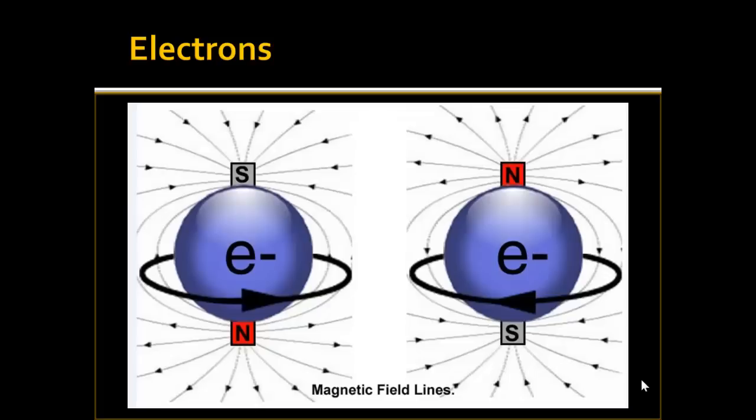They place it inside of a really strong electromagnetic field, created by electricity flowing through a coil, and by a conveyor, it goes into that field, and the magnetic force from the coil with the electricity running through it forces all of these domains, the ferromagnetic material molecules, to line up with all their north poles in one direction, south poles in the opposite. At that point, it is a very powerful magnet.